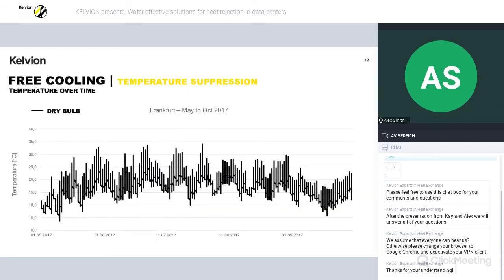Here you can see the temperature distribution for Frankfurt during a quarter of 2017, which I've included to show the effects of wet bulb temperature and how we can use this to our advantage. We know that ambient temperatures are sporadic and ramp up and down with time, which can be seen here. When designing a unit for a site, peak temperatures have to be considered. If we're going to design a dry cooler for this particular application, we have to design to 34.1 degrees Celsius, which is this peak right here. However, we can see that for the vast majority of this time period, that solution is going to be over-engineered because the average temperature is much lower.